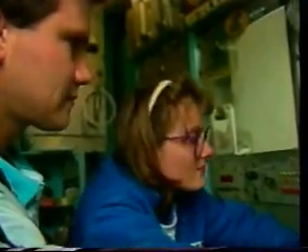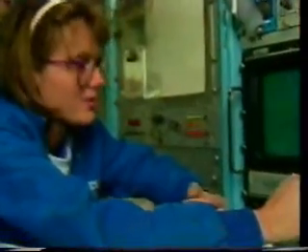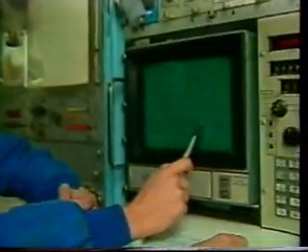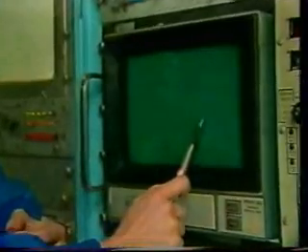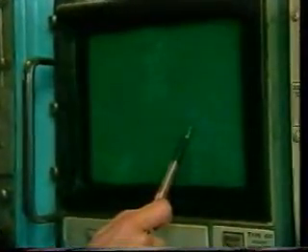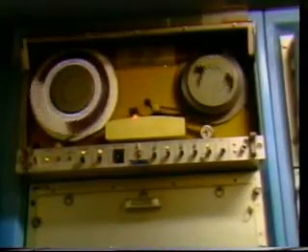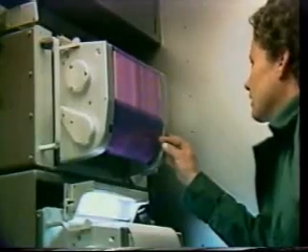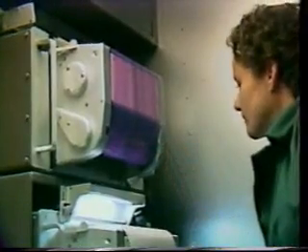As the string of tools moves uphole and passes through possible prospective intervals, the oil company representative studies the evolving curves with the logging engineer, and, if necessary, asks for a rerun over critical intervals. As logging proceeds, a permanent record of digital data is made on tape, and a visual record of tool responses is made on film.